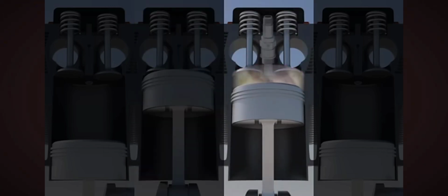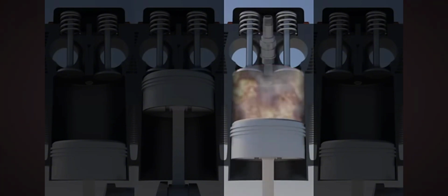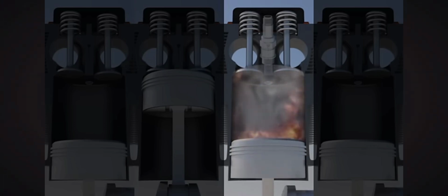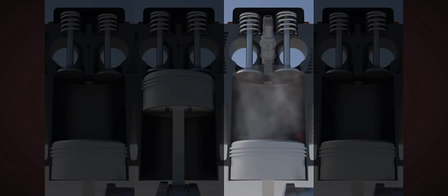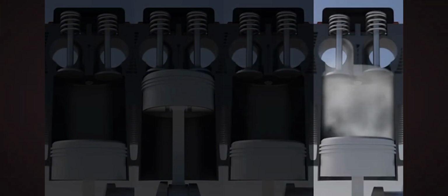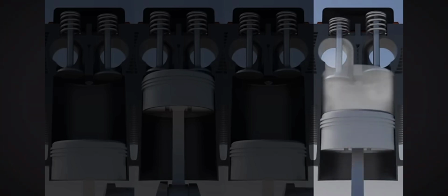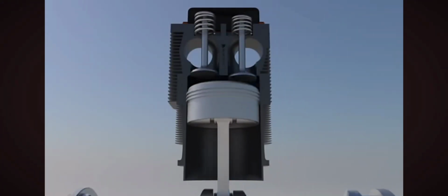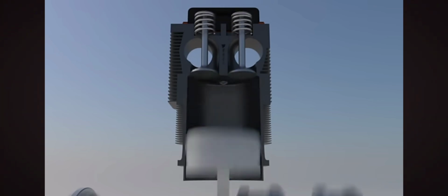Two spark plugs at the head of the cylinder each let off a spark, which ignites the fuel mixture and makes it combust. This controlled explosion pushes the piston back inward towards the base of the cylinder, which in turn rotates the crankshaft, and therefore the propeller. Finally, we reach the last stroke, exhaust. During this phase, the exhaust valve opens, and the piston moves back towards the cylinder head, pushing out the combusted gases, commonly called exhaust. Then, the process starts all over again, repeating thousands of times every minute.